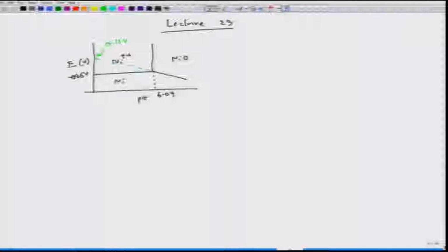And we could also see how we can make sure that this region belongs to nickel, this region belongs to Ni-H2O, and this region belongs to Ni plus plus. This also talks about the stability of those phases in those regions in that E versus pH diagram. Moreover, each line indicates the equilibrium between phases. For example, this line indicates Ni plus plus and Ni, this line indicates Ni and Ni-H2O, and this line indicates Ni plus plus and Ni-H2O.